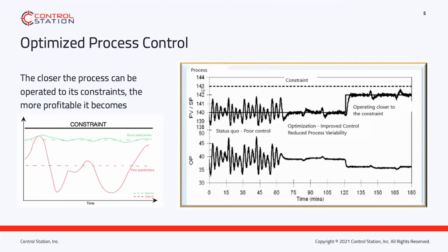A little bit about disturbances. Disturbances can lead to non-optimal production and are normally variables that are not controlled and can cause changes in the process. Disturbances can be changes in the feed, for example, temperature, composition or flow. Other disturbances can be process dynamics, changes made by an operator, or failure of equipment, just to mention a few. Through tuning, disturbances can be minimized but not removed. The best way to remove a disturbance from the PID is to find the disturbance and fix it at source.